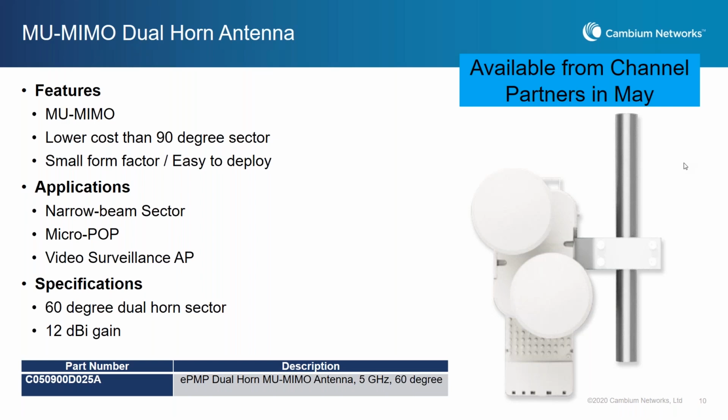So you're really focusing the energy and the beam forward from the antenna, reducing the side lobe and the front to back interference that might be coming from sources behind you. So it's a perfect application for lighting up a particular direction, a community or village, or inserting additional capacity or coverage to expand that network.